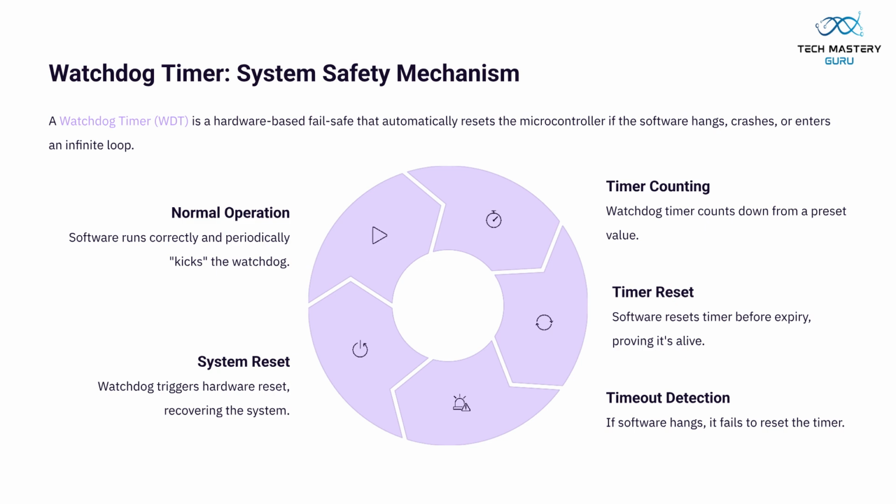A watchdog timer is a critical hardware failsafe that automatically resets a microcontroller if the software hangs or crashes. It functions by requiring the software to periodically kick it. Failure to do so results in a system reset, ensuring reliability.